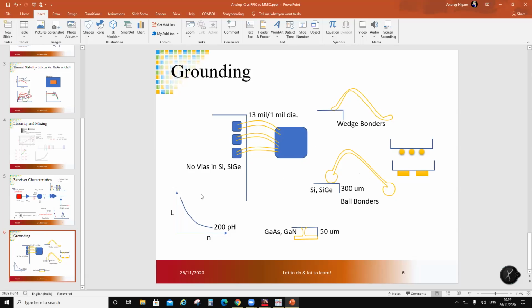I'll tell you lots of things with SiGe, where you cannot just take the model, design at 80, 90 gigahertz, and then say, my amplifier is blowing up, hot and cold. Why? You have to picture the die, see which parts are blowing up and why.